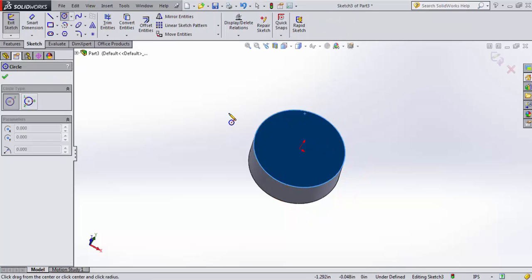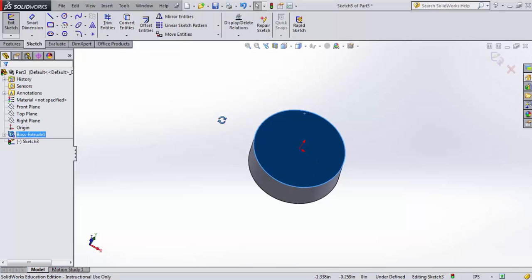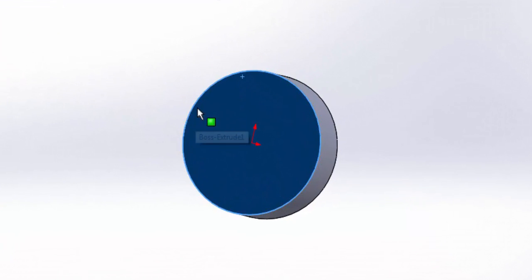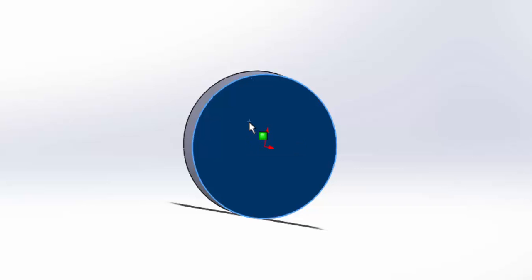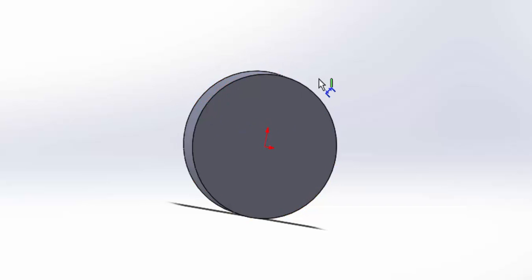Now, SolidWorks has a bunch of little shortcuts that I want to show you as well. When you're in a sketch, if you hold down your right mouse button and drag to the side, it opens up a set of tools. This is a quick shortcut way of getting different commonly used tools. So you can see here when I drag right, it gives me the option of a circle, the dimension tool, the line tool, or the rectangle tool. So this is a quick way to grab what you want and keep moving on.